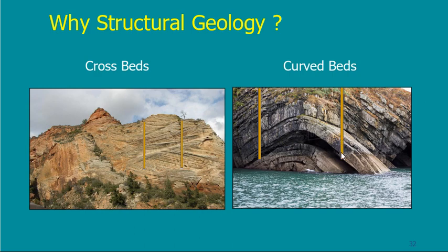Curved beds. This, by the way, is very, very important, because look at this borehole and look at this borehole. You will find that the findings of both boreholes are more or less identical. Usually, if I say that this is a layer and this is the same layer, I will just pull a line between them and say that this is a horizontal layer, which is not the case. It is a curved layer.